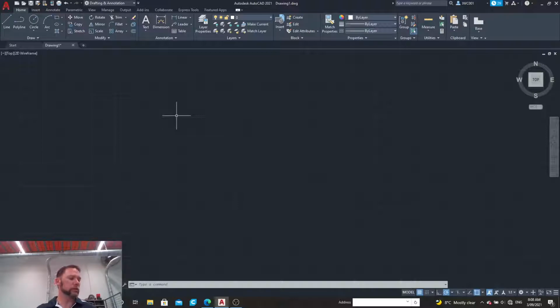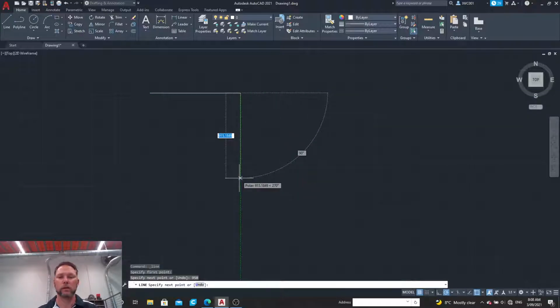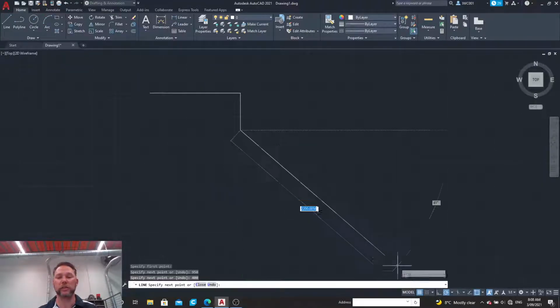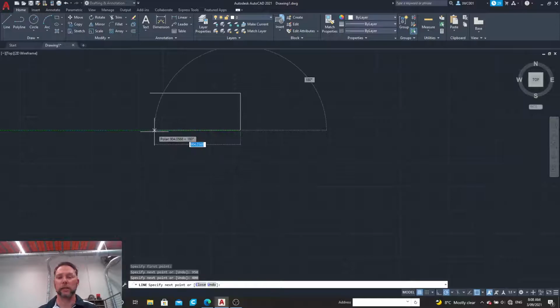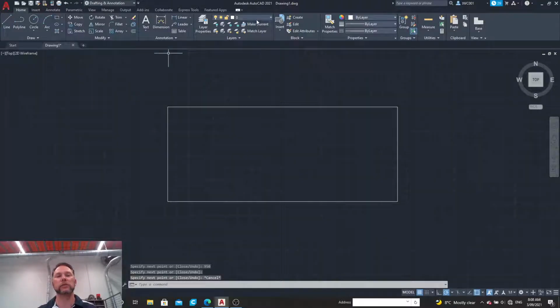And now I'm going to draw this in 2 dimensions, from a top view. So first I'll draw the space that my frame and my legs are going to take up. So it's going to be 950 mils long, 400 mils deep. So I'm just angling it. It's locking in every 90 degrees, which is why I set it in my polar tracking. 950 mils long again, back here, and then I hit escape. So there's my framework.